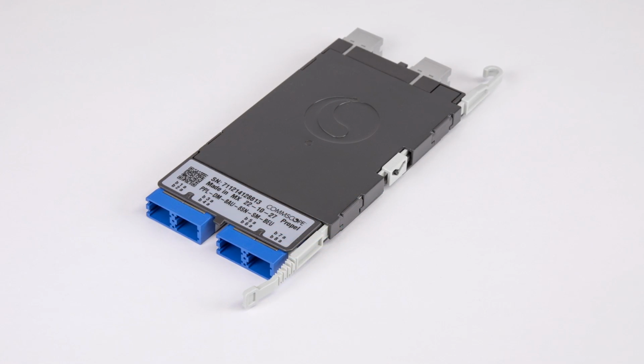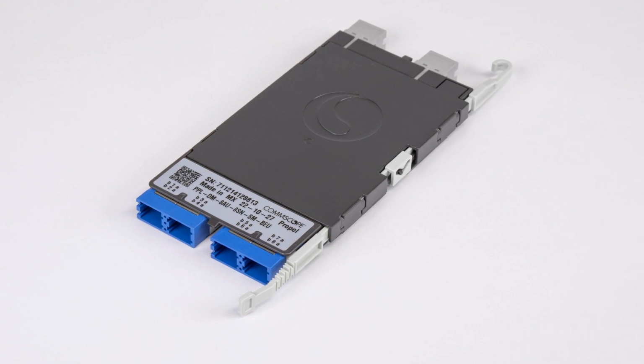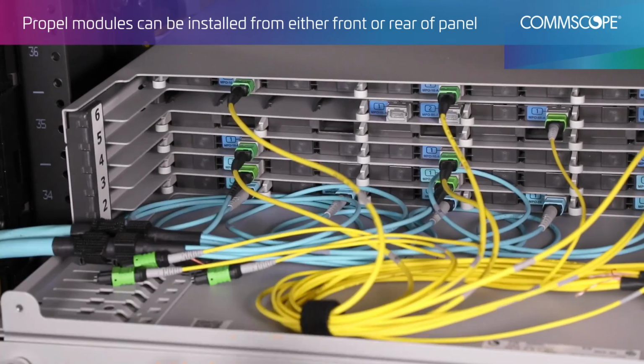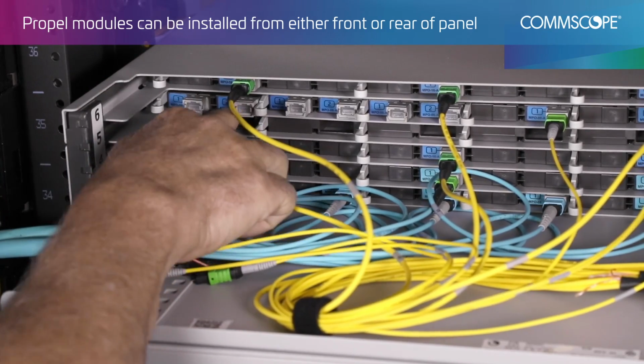Now we can install our MPO to SN module, which enables us to increase fiber count within the same panel. Insert the SN modules onto the blade. Align the rails on the blade with the slots on the bottom of the module and guide it into position until it locks into place.